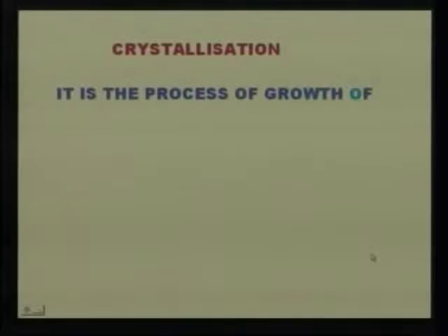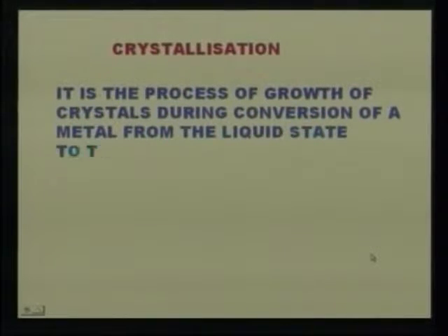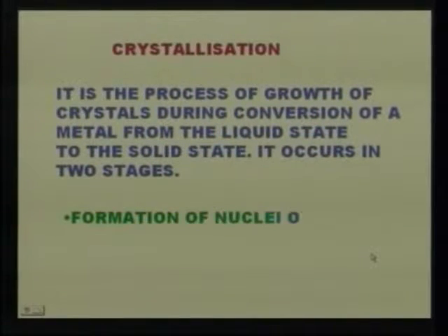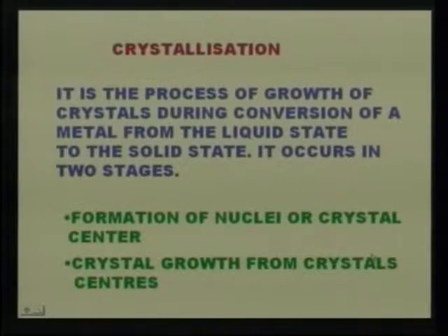Now, what is crystallization? It is the process of growth of crystals during conversion of a metal from the liquid state to the solid state. It occurs in two stages. Those are formation of nuclei or crystal centers, and the second one is crystal growth from crystal centers.